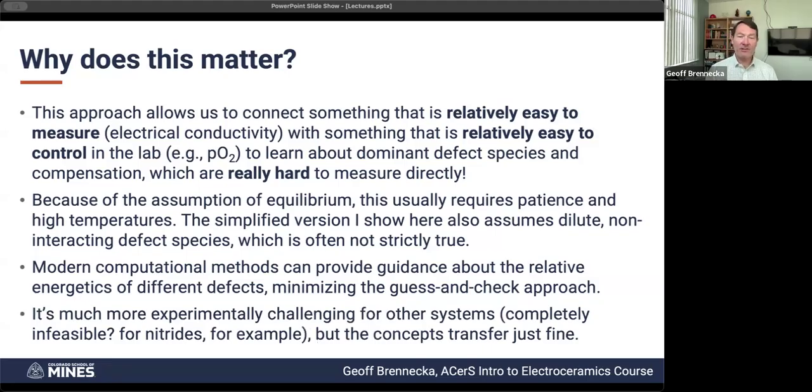you can also, like I mentioned, do this for nitrides, you can do it for sulfides, you can do it for all sorts of other materials. Carbides, it's a lot harder for carbides than for nitrides when you've got more challenging kinetics associated with it. And if you've got conductive nitrides or conductive carbides, then maybe the number of free electrons doesn't really affect the conductivity enough that you can make a measurement like this that will tell you the kind of thing that you want to know. But you can still walk through the same process and go back to Shannon's question. Maybe under these scenarios that you can see that the bulk density should really change a lot, or the lattice parameter should really change a lot, something like that.